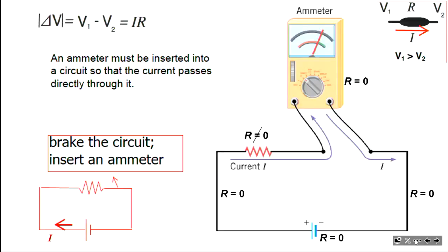And if we know the voltage, 5, and if we know the current, well, let's say 0.3, we can calculate the resistance of this bulb, more or less. The resistance will be equal to voltage over current. That's it, in ohms. Well, this is how we do it with a simple circuit.